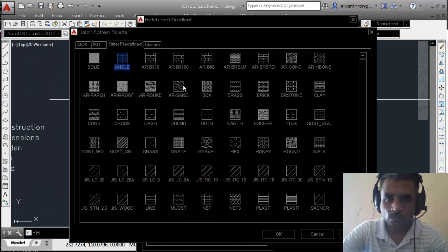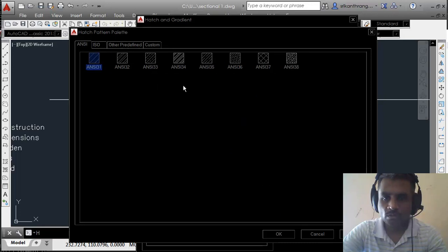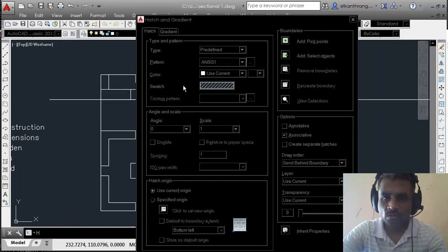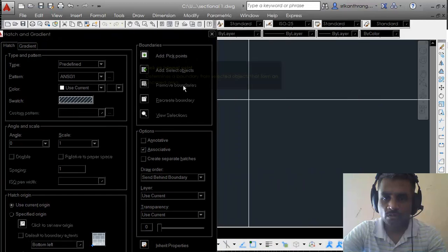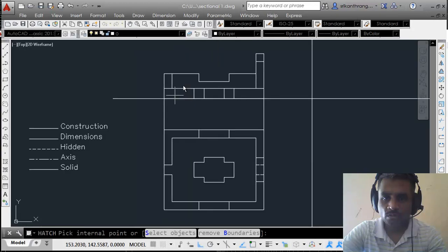So we need hatching over here, here, and here. These are 3 regions where we want hatching to appear. Just press enter 2 times, and you can see the hatching has appeared. So this completes the sectional front view and top view. All we have to do now is to get the side view.